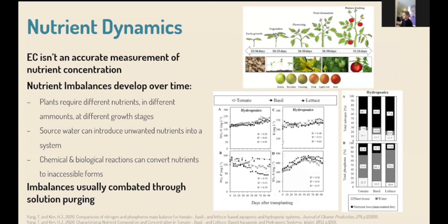So you're getting anoxic spots in your system where there's low oxygen for various reasons. Denitrifying bacteria are being recruited from the environment. They'll always be recruited in, even if you sterilize your system. They come from the environment, they go where the nitrogen is, they turn the nitrates into nitrogen gas and it leaves your system and it's just gone. So that's more of a biological reaction.